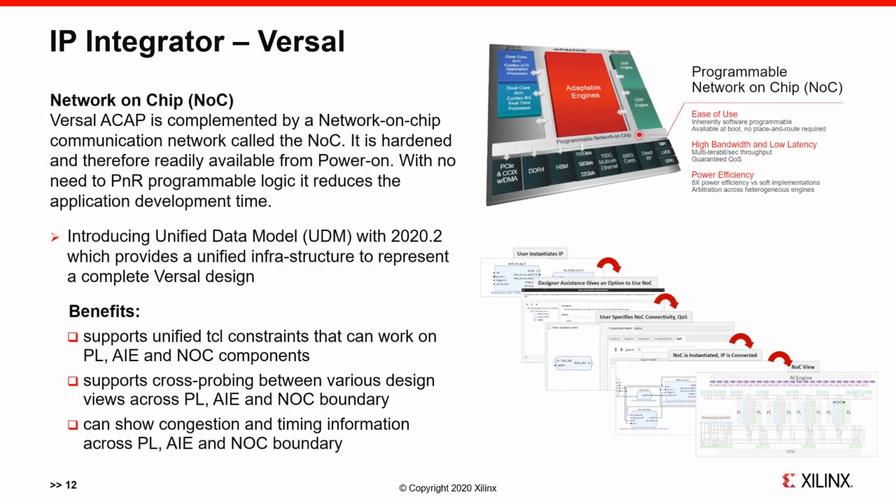Heterogeneous compute requires a high-performance network of connections to move data with efficiency and yet be simple and flexible. So Versal ACAP is complemented by a new network-on-chip communication network called the NOC. This communication infrastructure provides high performance and coherency support.